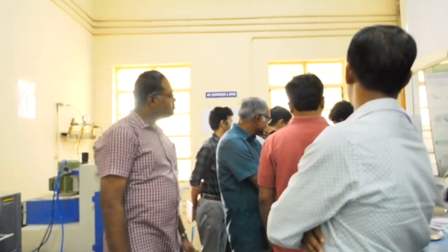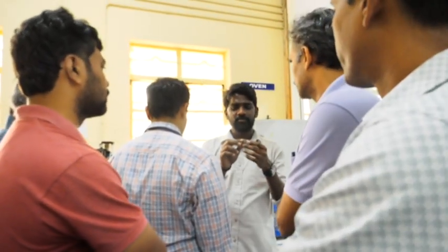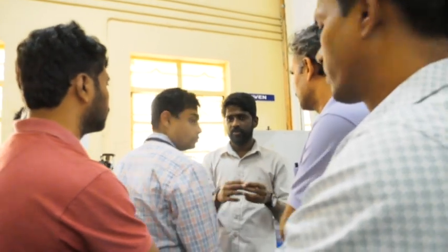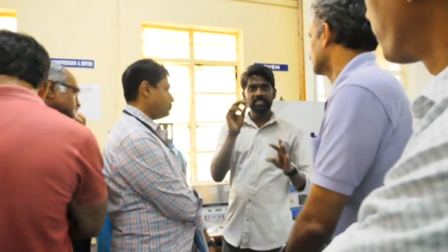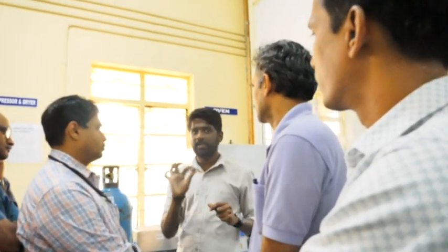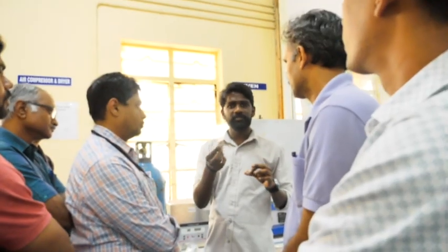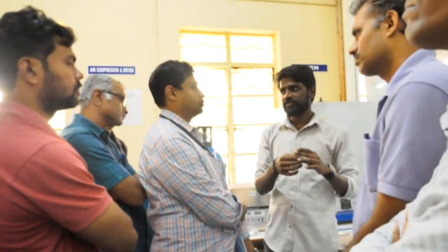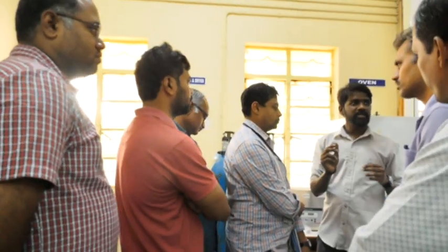This ultrasonicator is for cleaning, because in order to remove the powder particles it takes more and more time. So right now we are using only the ultrasonic for especially these lattice structures in order to remove the powder particles, like unsintered powder particles or unmelted powder particles. And for surface treatment, I told you initially, bead blasting will be another application. Okay, got my point? Apart from that, any queries?